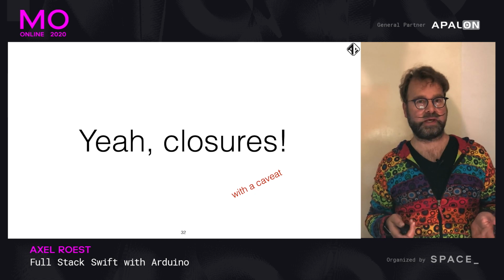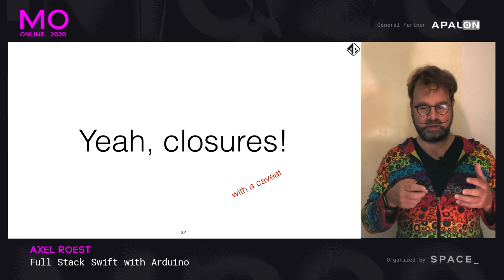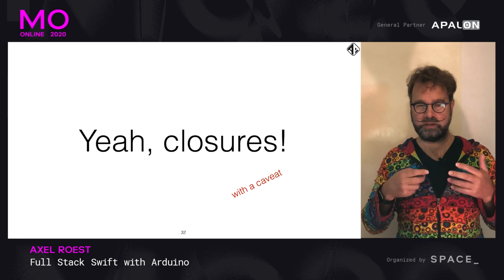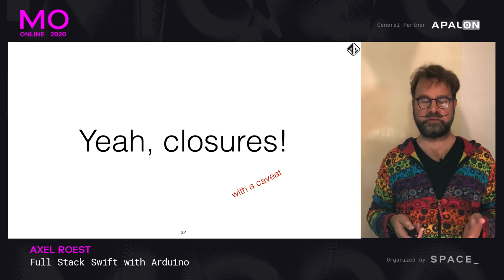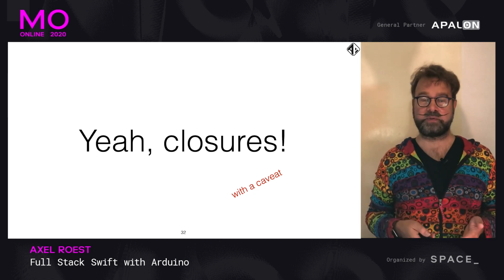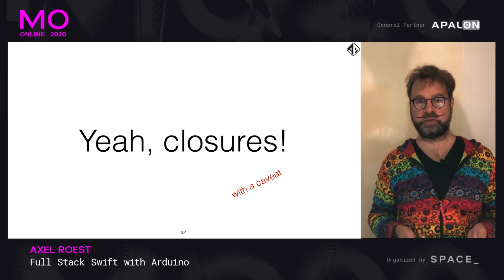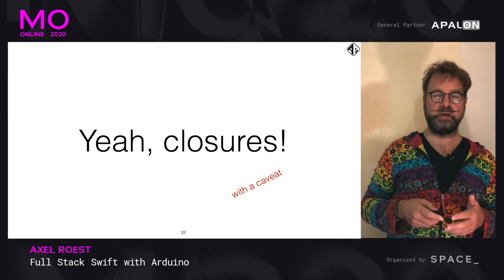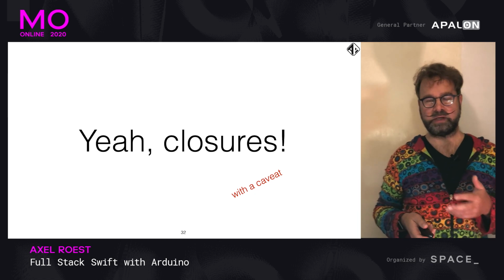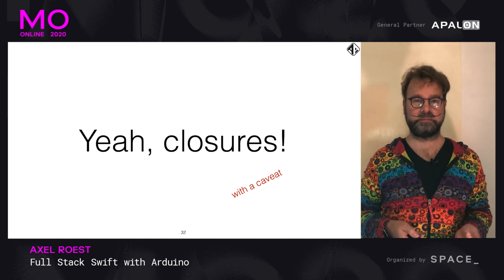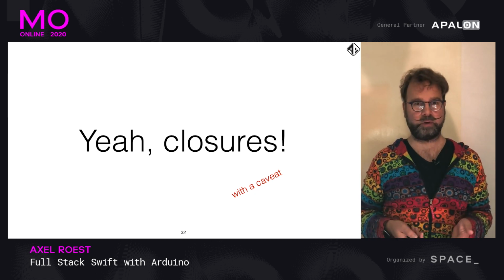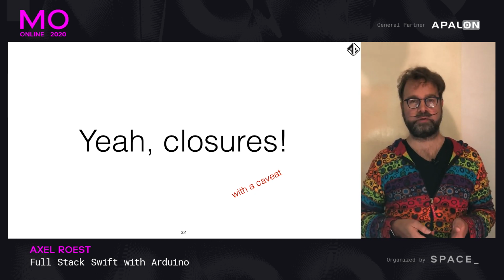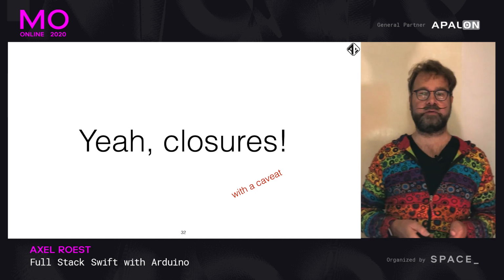But that also comes with a caveat, because closures inside structs which encapsulate self need a lot of runtime support. And again, we don't have much runtime support. So closures can exist, but you can only access global variables, which is okay. If you want to learn more about this, there's a special YouTube talk from the implementer of Swift for Arduino.